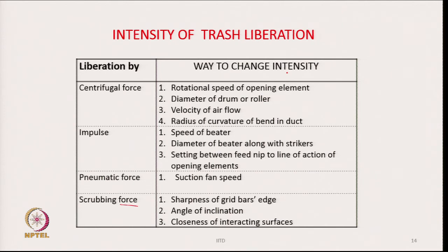For impulse, it is the speed of the beater or the diameter of the beater along with the strikers, that is the tip of the strikers, and the setting between the feed nip to the line of action of the opening elements. This setting is also very important for impulse.